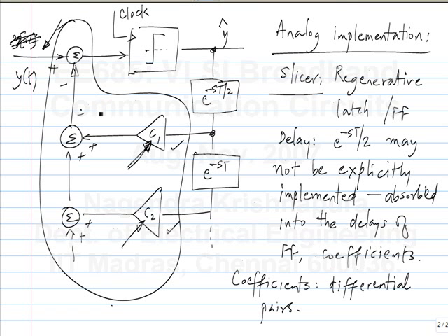So you design the circuit and the biasing, because the delay of all these elements depends on their own parasitic capacitances. It's like the delay of an inverter. It depends on the gm of the inverter and the parasitic capacitances. The parasitic capacitance varies with process and temperature. The gm varies with process, temperature and the bias condition. So you adjust it so that the variation is within manageable limits.